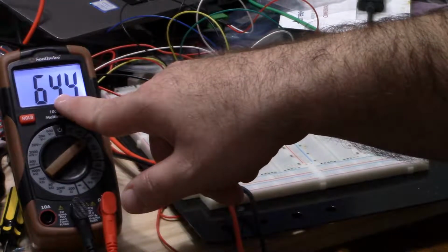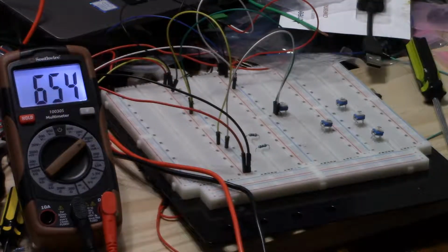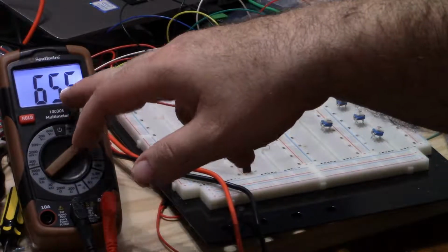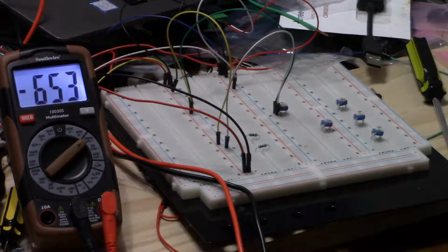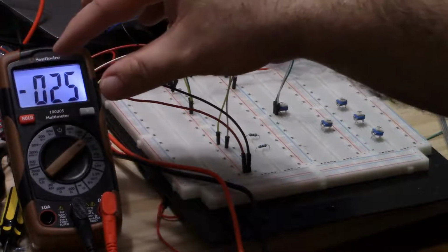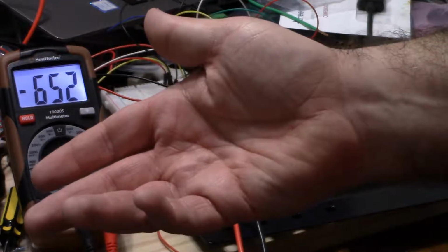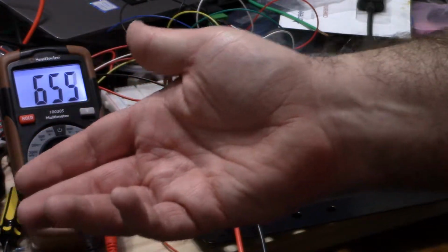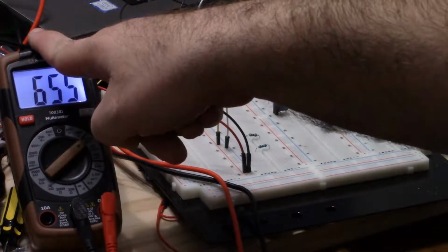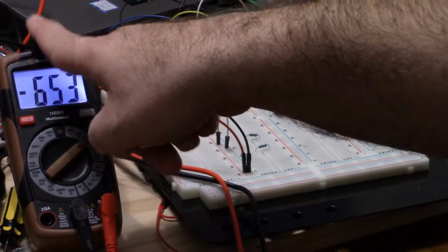It's not measuring a changing signal, it's a DC signal. So 655 divided by 1 million, that's 6 zeros, 0.000655 amps, times about, let's say, 27 ohms, equals 0.0176 volts, so it went down again. So it actually seems like I was very wrong. It must be a series connection, because this is in current mode, so it's not really adding any significant resistance.